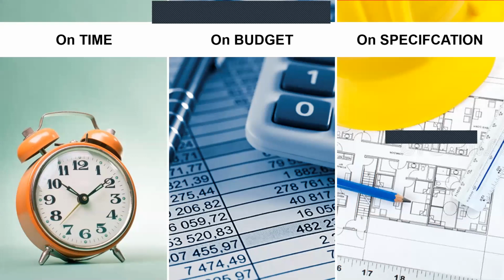If they have laid down a floor, what is the flatness of the floor, what is the height of the building, what is the verticality of the building, how good it is against the BIM model, which is a Revit model. So they try to make a combination of 3D scanning running on a construction site and comparison with their BIM models on a day-to-day basis, so that they can stop a mistake from happening at a very early stage, so that they can control time.